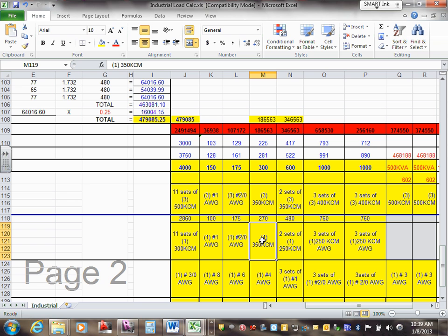Okay? The last thing, guys, grounding conductor, equipment grounding conductor, or grounding electrode conductor here. These are two tables you're using. You're using 250.66, and this is also written in it, or 250.122. Other than the service, everything is going to be 250.122. The service is the only one that's going to have 250.66. Also written in that one. Any comments, my friends? Any questions?